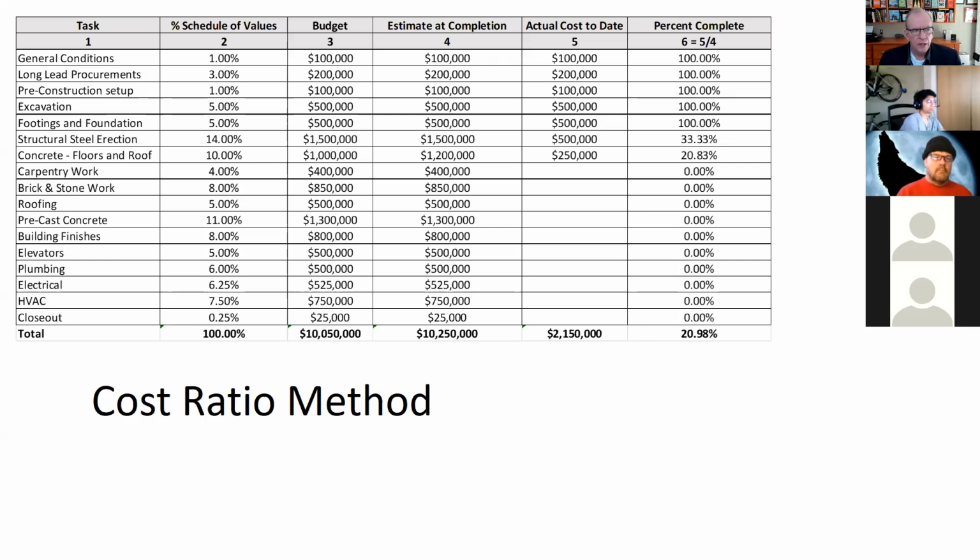On the other hand, you as a contractor have to worry about how you pay your suppliers and your people, and what if this client goes bankrupt partway through? Then I'm stuck, right? So it's this push and pull that is always going on. Usually, if it's a large project, the client will hire a consultant to review the schedule of values to see if it makes sense proportionately with the overall costs. This happens in pre-construction, so that usually gets settled there.